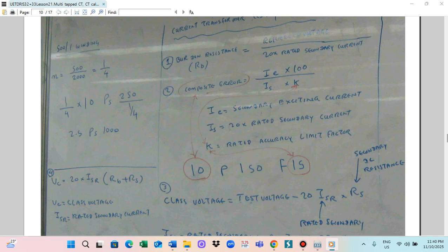And also there is the AC polarity check for the 3-phase CT. So for the 3-phase CT we connect like this. The secondary windings are combined and connected to an ammeter, and the primary windings are connected in zigzag to the load. And we inject the current. If your connection is all right, all magnetic flux adds together so that the ammeter will indicate a reading. When the ammeter indicates a reading, you can put the dot here. Dot means the current entry point. If the ammeter does not indicate, your connection is wrong, so you have to change the connection and test again until the ammeter indicates, and then you can put the dot like this. So this is the CT testing.